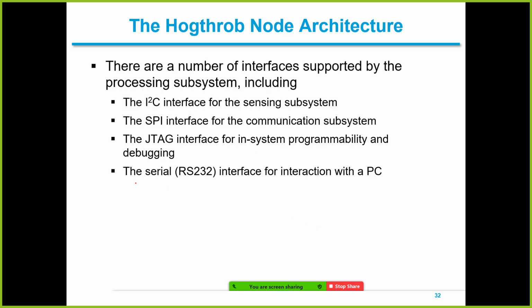And here for the serial communication interfaces, we have I2C for the sensing subsystem, SPI for the communication subsystem, and JTAG for in-system programming and debugging.